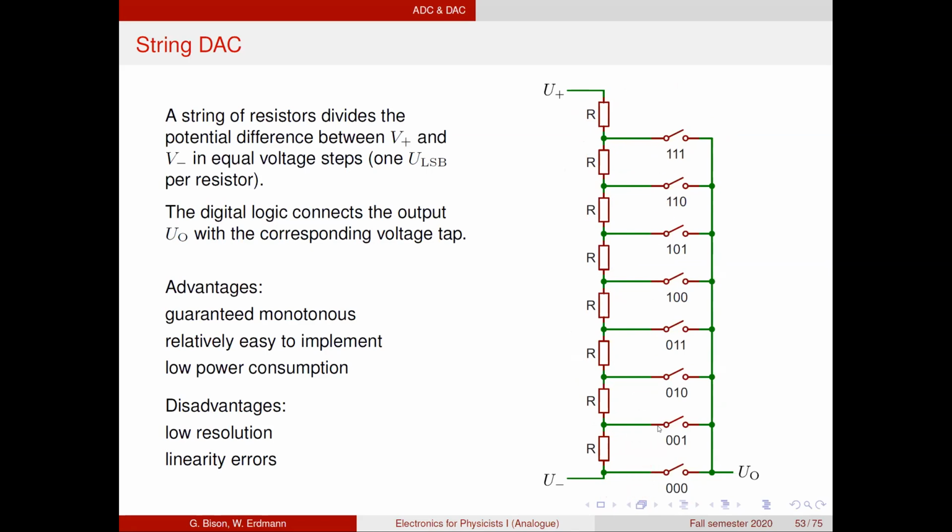For this 3-bit DAC, there are 8 different values. And one particularity that you see here is that we can generate 0. So this is connected to the minus reference voltage. Let's say this is ground. So we can produce 0 output. Our 0 digital code produces 0 output voltage. Our 111 digital code produces not exactly the plus reference voltage, but is removed by 1 step. In order to represent the plus reference voltage, we would need 1 more bit.